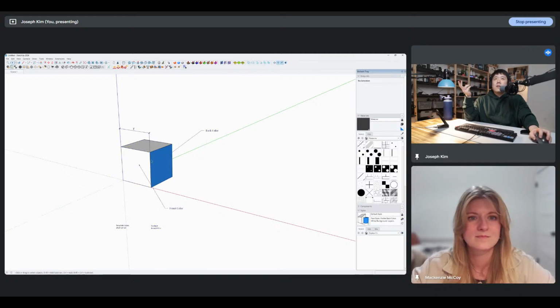One is the front face and the back face. The back face will play very much into your model organization and also in rendering. Understanding what your back faces are or where those things are visible is very, very important. Or let's say you want to make sure they're not shown in your model. You always want to make sure that your models are oriented properly so that you don't have back face issues, because some of the renders do not render the back faces, and so some of the materiality doesn't show correctly if you don't have that set up correctly.